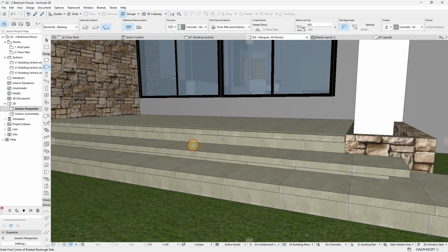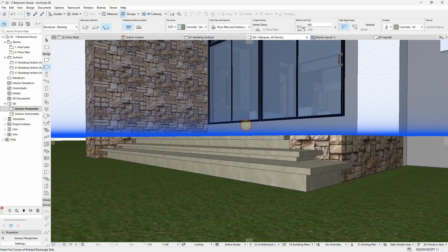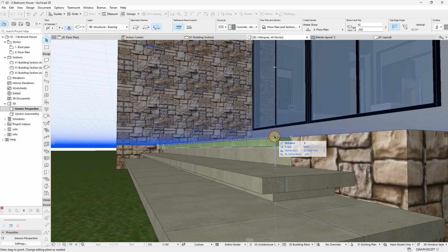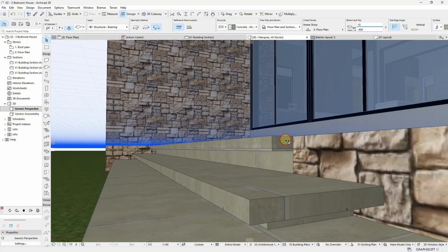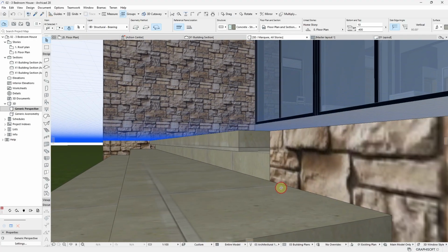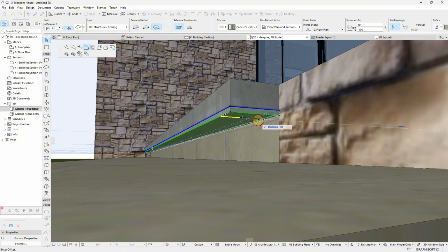Something like that. And then if you need to put a strip light under, it is still simple. Get this slab, drag a copy of this, Ctrl-Shift-D, bring it here, change the height to 10 millimeters. After changing it to 10 millimeters, you come underneath here, a little bit here, and you drag it inwards by 90.